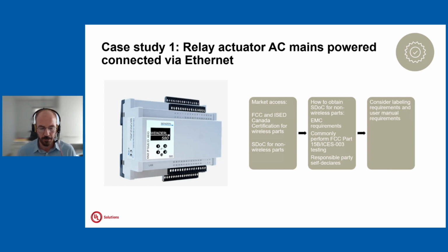If a device is connected by DC, it's DC power, but DC power is at some point connected to the AC mains through an AC-DC converter. Then conducted emissions are also applicable, with a representative AC-DC power supply. If instead the device is powered by a non-rechargeable battery, then it cannot be connected to the AC mains by any means, and conducted emissions may not be applicable, only radiated emissions. Okay, so this is just to show you that FCC only considers the emissions requirements of the EMC.